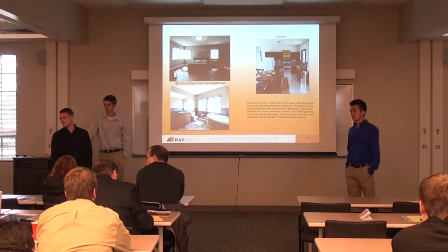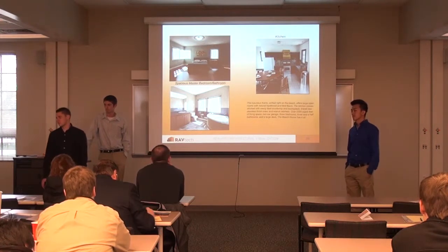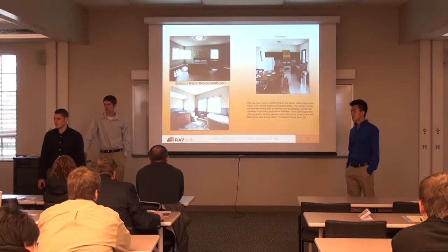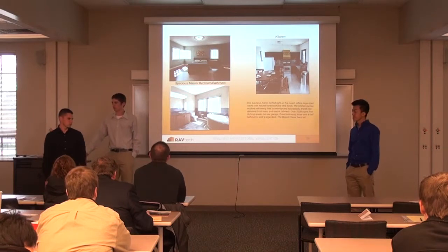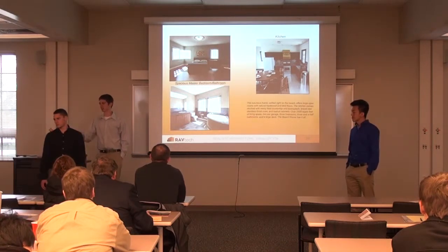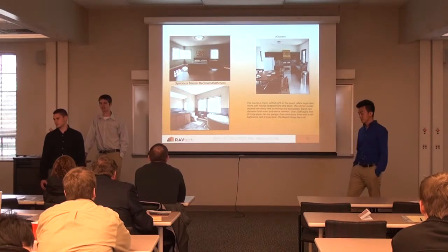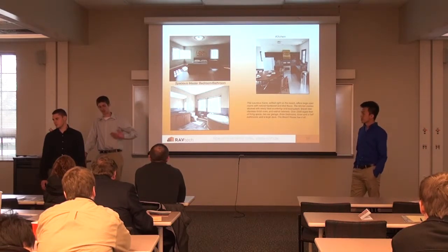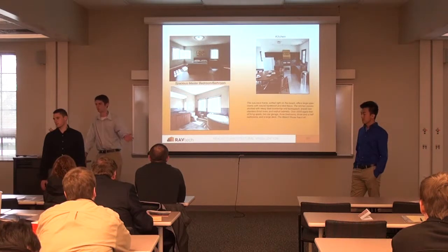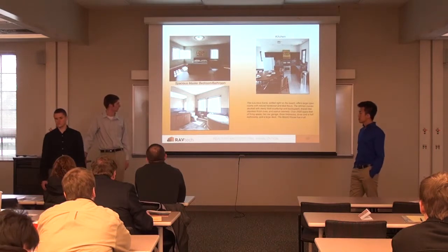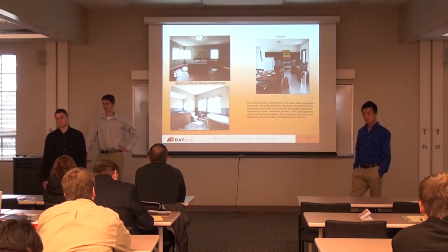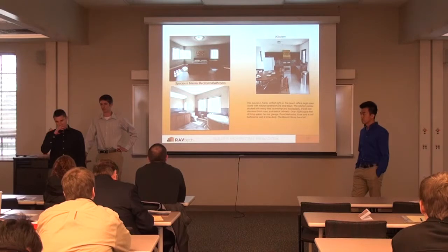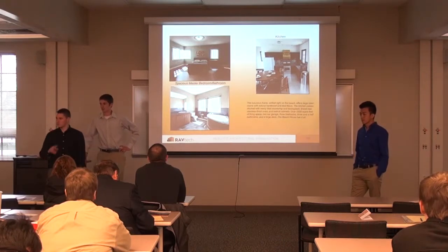I don't know so much about 3ds Max, but is there a final gathering setting in the render? Have you tried upping that, because that might help with shadows? That was actually one of the things I found, the final gather settings. Once you broke past 200 or 300, you started spending hours rendering, and some of them never looked that much better. I did one kitchen at 1,000 final gather and another at 150, and they looked almost identical. Obviously if you up it, your render time will go up.